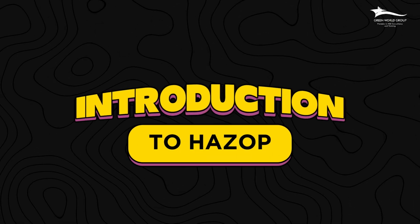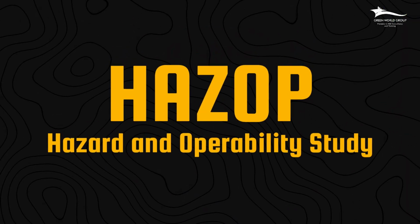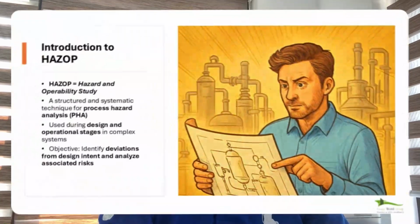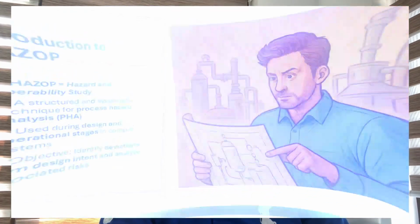Introduction to HAZOP. What does HAZOP stand for? HAZOP stands for Hazard and Operability Studies. It is a structured and systematic technique used in process hazard analysis, commonly known as PHA. This method is especially useful during the design phase of a system, and it continues to be beneficial throughout the entire operation.